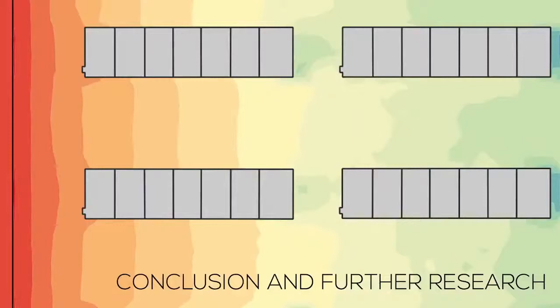We have successfully created noise maps, comparable to those produced by our clients, by directly using a TIN model of the terrain. We know how several of the differences are caused and how they could be solved. The concept is therefore proven to be an interesting alternative to the currently used height lines. The main challenge was to make the concept compatible with many different situations, which was successful in most cases.